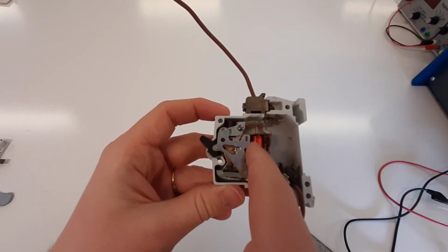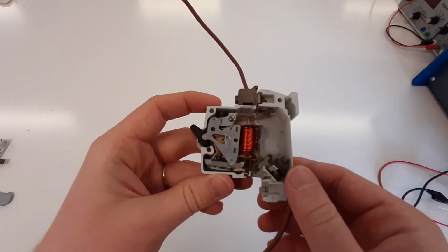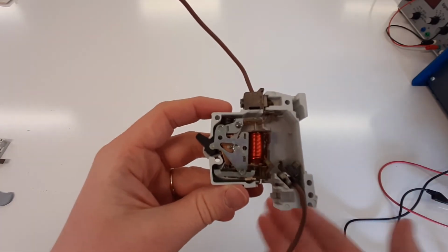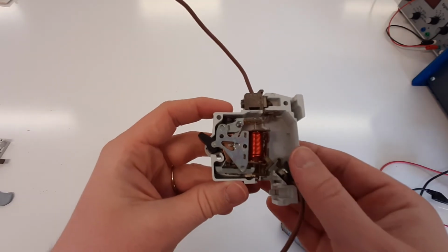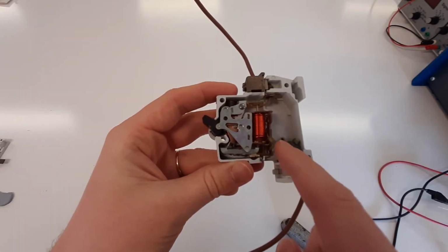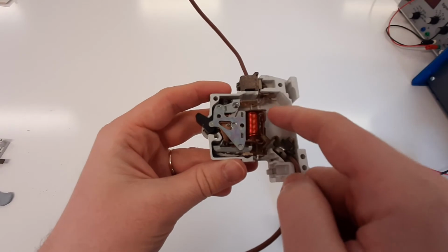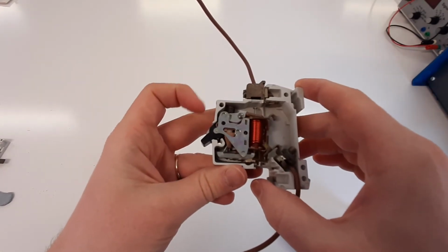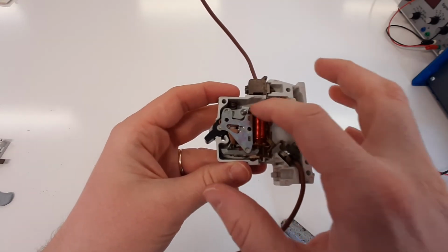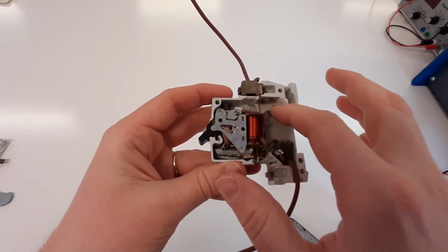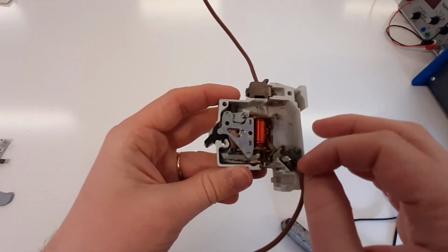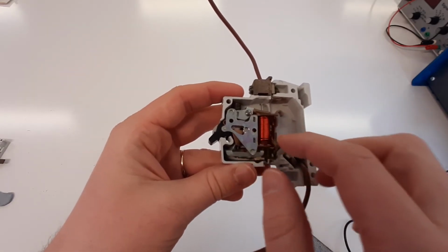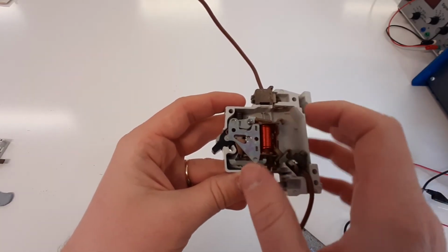Now the current isn't strong enough to activate this electromagnet yet until we get a sudden surge of current, which could damage components, and it could also damage and start fires in your house. So when there's a big current, the electromagnet starts to activate, and that pulls the arm down. And that means that there is now no longer a connection between this arm and that arm, so current stops and everything's fine. Of course, the electromagnet is then going to deactivate because there's no current flowing.